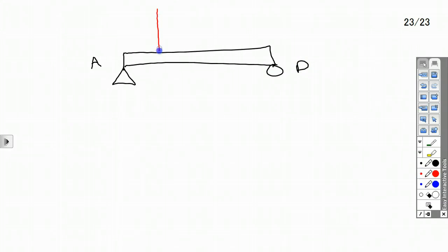So I have an 8,000 pound force coming down right here at point B. I'll call that FB, force at B, which is equal to 8,000 pounds. I have a force right here in the middle that's coming down at a 45-degree angle, which is 4,000 pounds. And I've got a force coming down here again, which is 8,000 pounds, and we'll call that point C. I really should have put another point in here. I'll throw this in as E, even though it's in the middle, but I'll go by what the picture says. And this is at 45 degrees.